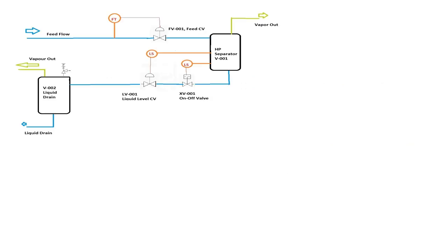So this is the process, and we have discussed this process during the HAZOP analysis also. For the HAZOP we considered the same process, so you can correlate how things are actually done. First there will be HAZOP, and from the HAZOP points, if there is a need for quantification, then we go into LOPA. From the LOPA we check whether there is any requirement of any SIL, or if there is a requirement, what will be the categorization of the SIL, right?